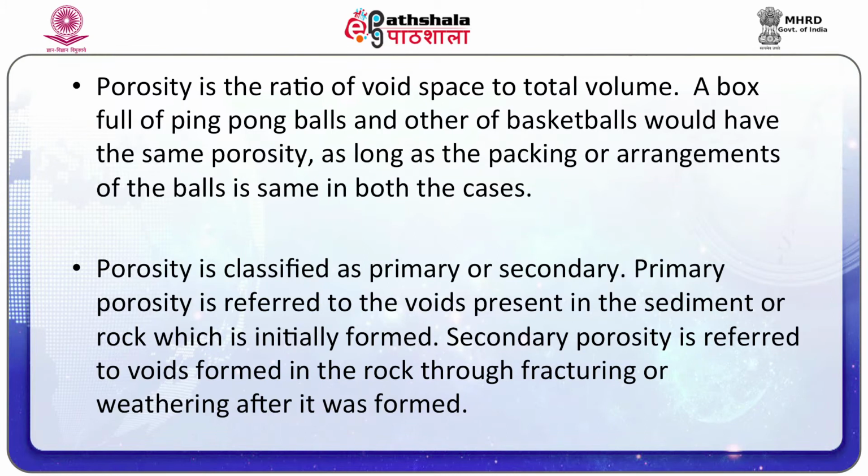Particles exist in many shapes, and these shapes are packed in a variety of ways which increase or decrease porosity. A mixture of grain sizes and shapes results in lower porosity. It is not affected by the diameter size of the grain. Porosity is the ratio of void space to total volume. A box full of ping pong balls and another of basketballs would have the same porosity as long as the packing or arrangement of the balls is the same in both cases.